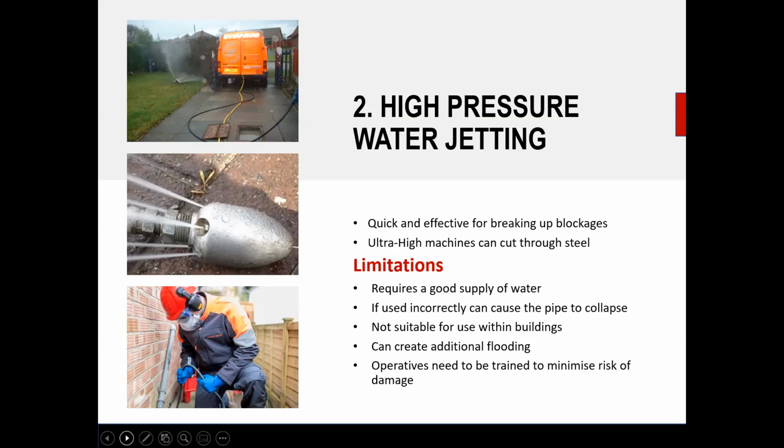It's not suitable really for use within buildings, especially multi-story buildings, tower blocks, etc., because you can't actually get the pump and the vehicle anywhere near the place where you want to work. With water jetting, you're actually adding water into the pipe. Therefore, if you've got an already flooded pipe, then you've got a risk of causing an environmental issue and subsequent flooding.